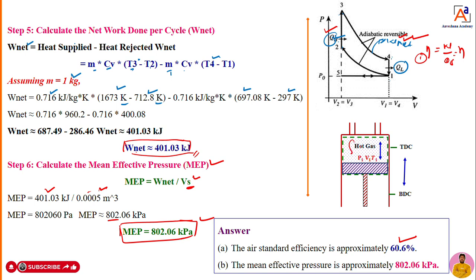Then when you are going to do combustion, when you are going to give a certain amount of heat, that is going to create some explosive force over the surface of the piston. Force means it is going to have a pressure. If you take the average pressure over the surface of the piston, you can call it the mean effective pressure.